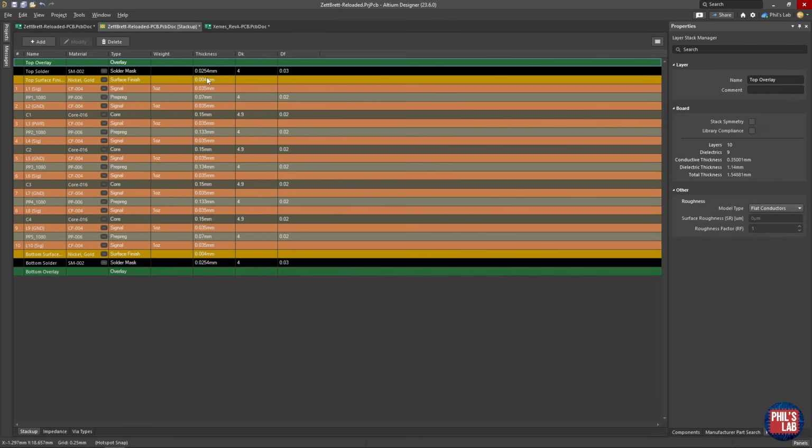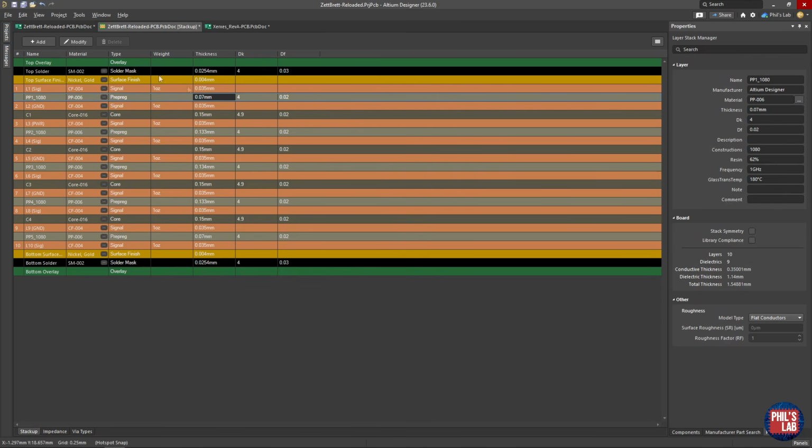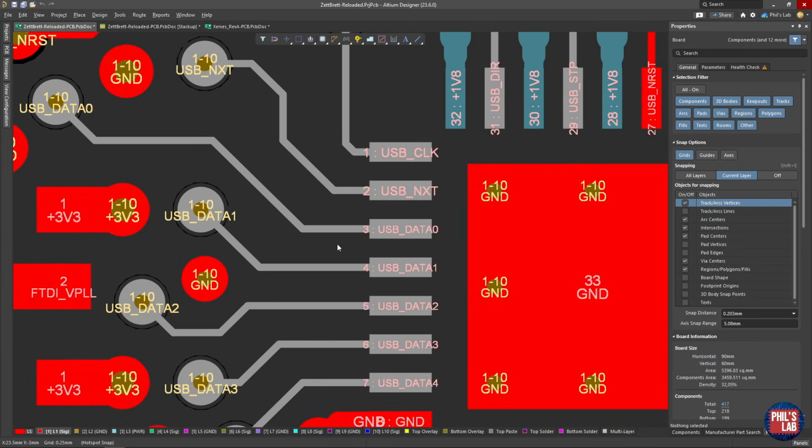For example, looking at the stack up of one of these boards, looking at layer 1 to its return path below, we have a dielectric thickness of about 70 microns. So according to the IPC guidelines, we want at least 0.14 millimeter spacing for an external layer trace. But let's go to the PCB. We can do measurement between these traces, and we have about 0.4 millimeters, so far wider than the IPC suggests, but this is what I always do.